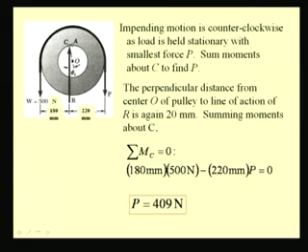So this problem illustrated how we can solve the problems involving journal friction by first finding the radius of the circle of friction and then displacing the reaction tangential to the circle of friction and then solving the problem.